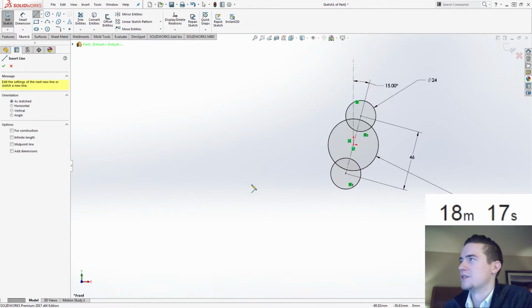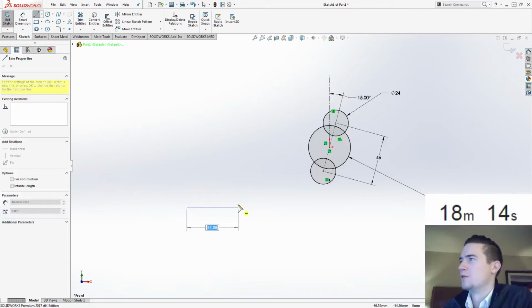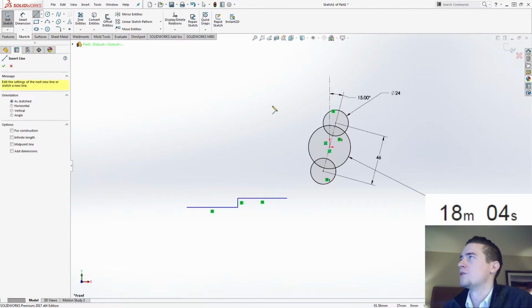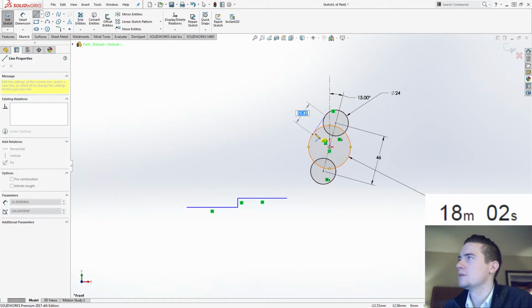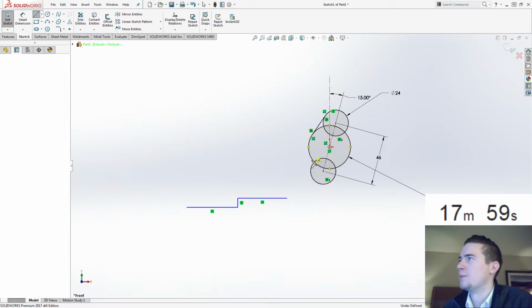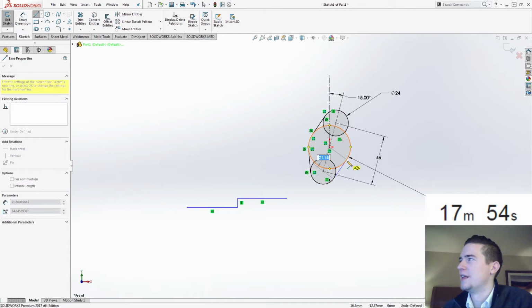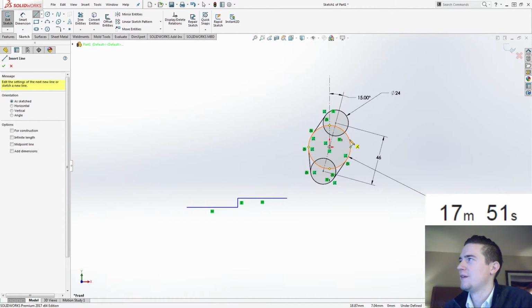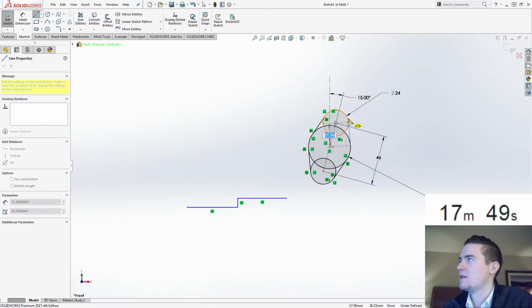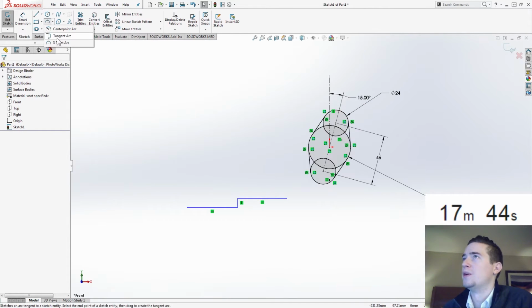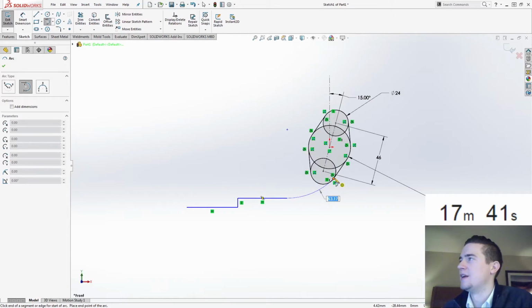So we're going to just kind of sketch this out in space. Start over, horizontal line, jog up, jog over, transition to an arc. That is going to end where? Oh, shoot. I don't know. Let's create some tangent lines, shall we? Similar to what we've done before. Hover the mouse over some of these arcs and wait for it to detect that tangency. Yeah, so now I know if I'm going to do a tangent arc from this point, it's going to end there.